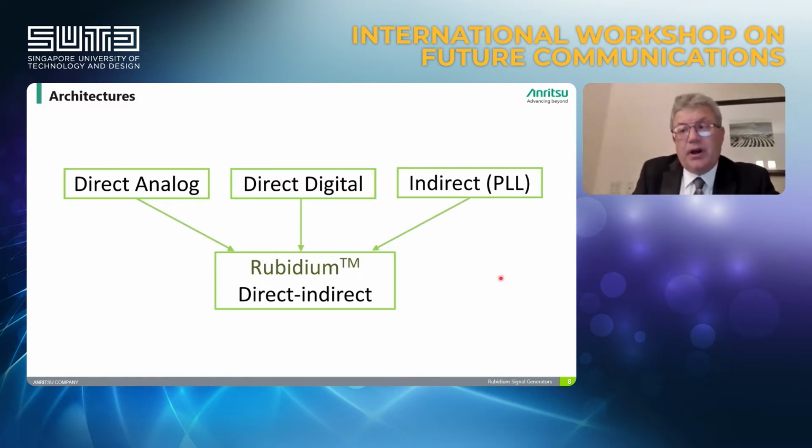In general, frequency synthesizer designers use various methods to synthesize a signal, such as direct analog synthesis, direct digital synthesis, and indirect or PLL synthesis. In our Rubidium signal generators, we use an innovative direct-indirect technique, which essentially combines and represents the best aspects of each method.